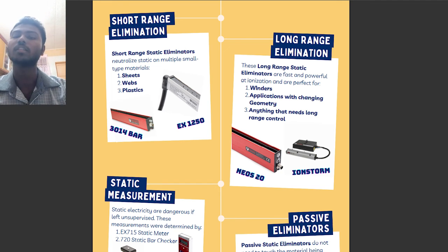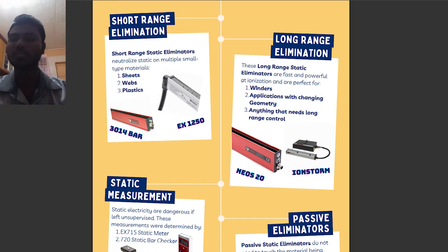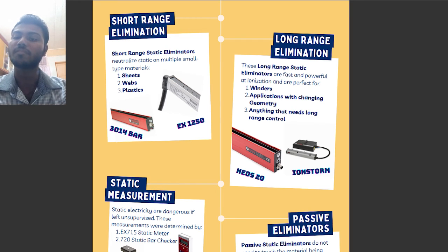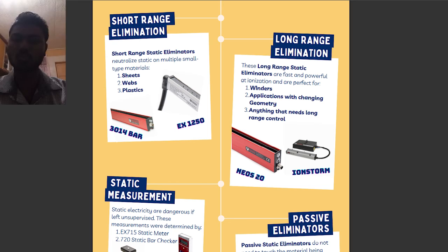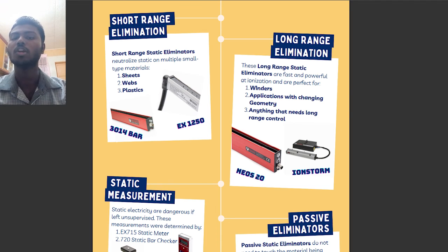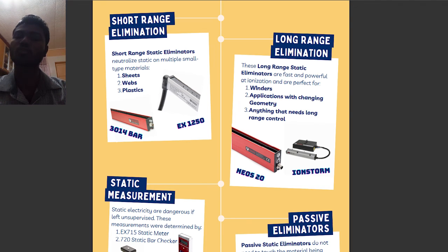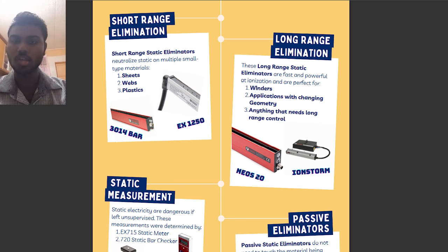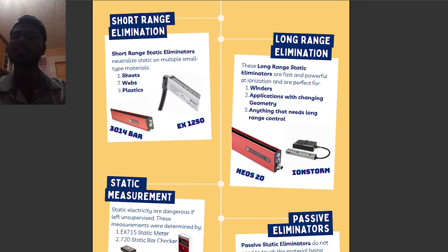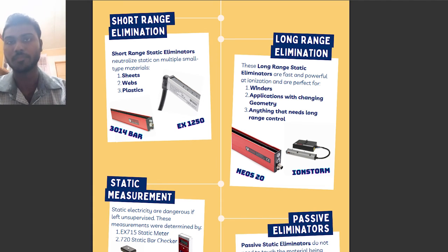However, the argument for neutralizing the molding as soon as possible is that it will prevent dust attraction from occurring. We often install small ionization air nozzles on the robot arms to neutralize the molding as soon as it is picked up. Using an ionized air nozzle or blower is beneficial as it helps cool the molding as well as neutralize the charge in the product.